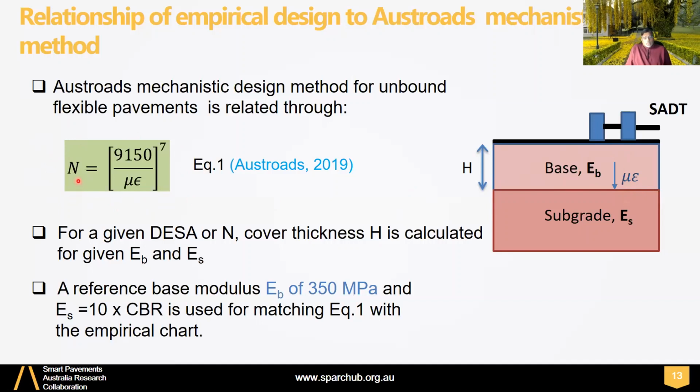So this formula tells you, if you have a certain vertical strain on the subgrade, here given in microstrain due to this loading, then the tolerable number of cycles or equivalent standard axles is given by this factor and this constant. So this is comparable to the chart.